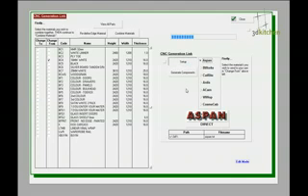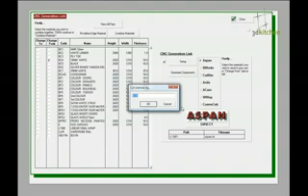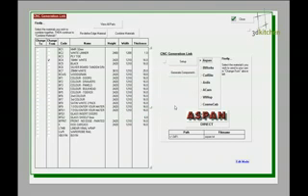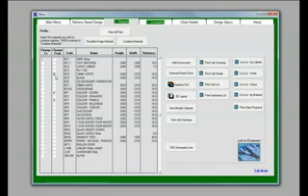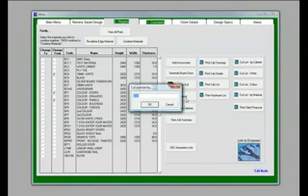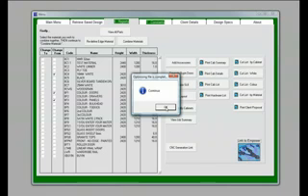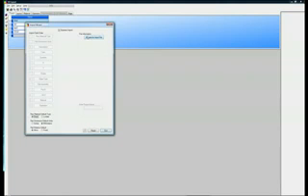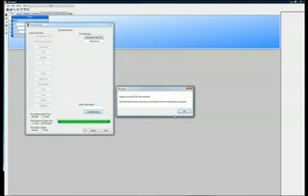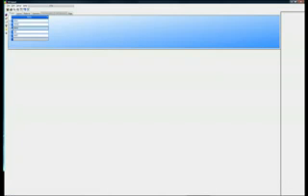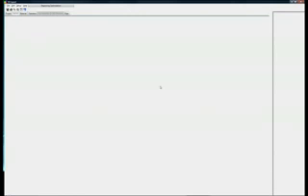We can export that data if we need to external programs for CNC. For those of you who need to go out to CNC equipment, we can export that to the CNC software. Okay, now we're going to show you the optimization, so we can optimize right within the product. So we can choose the board, we can import the panel sizes, they come directly in, we give them a name, import the files, and it brings in all the board types that we've selected, so they can be optimized all in one hit, whether they're color board, whiteboard, they can be all mixed up. The program will separate them out and optimize them in their material groups.